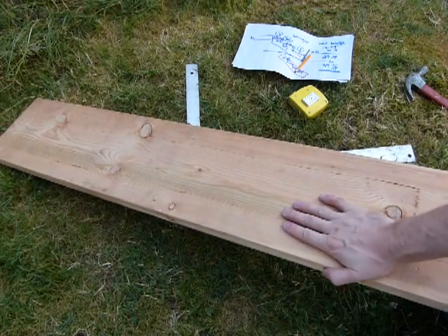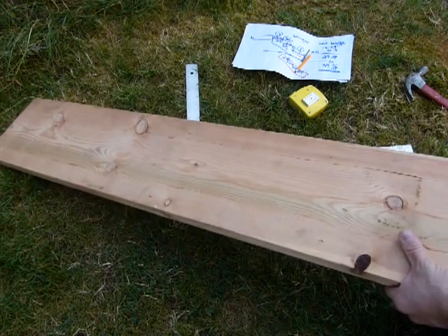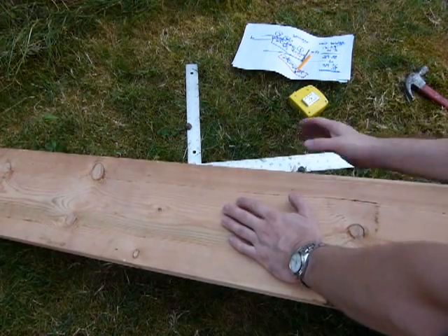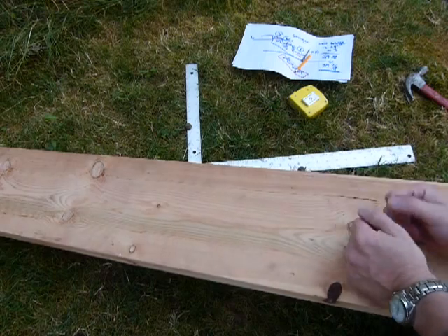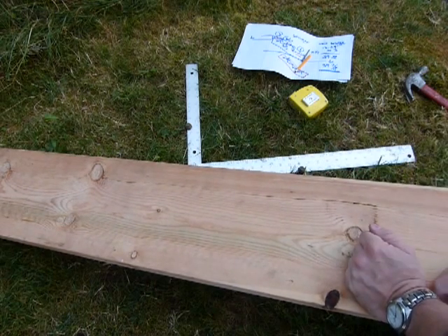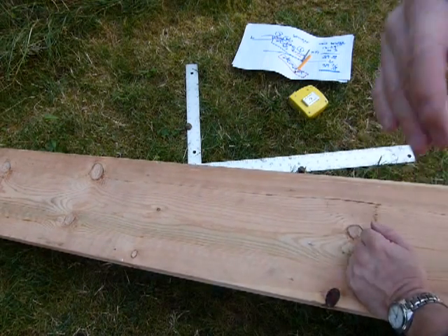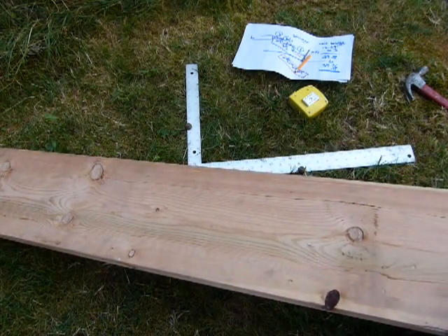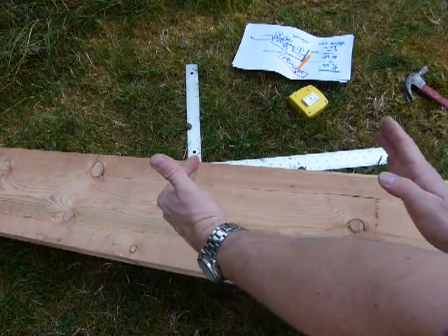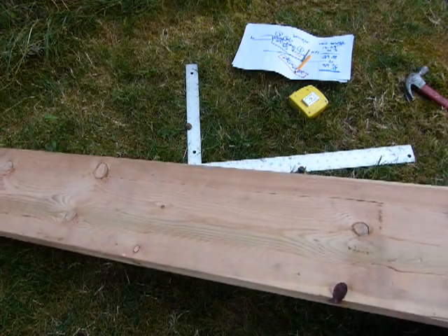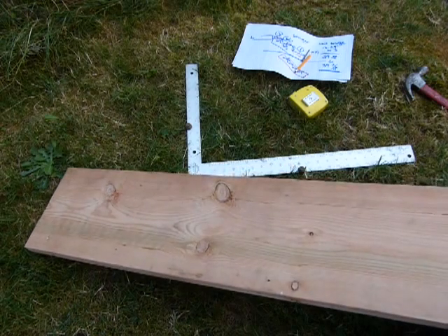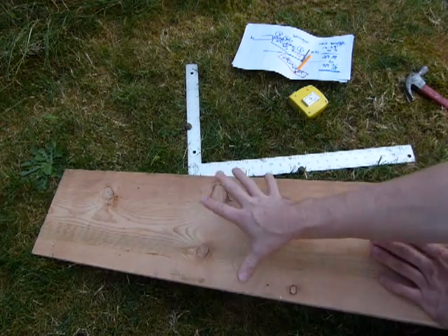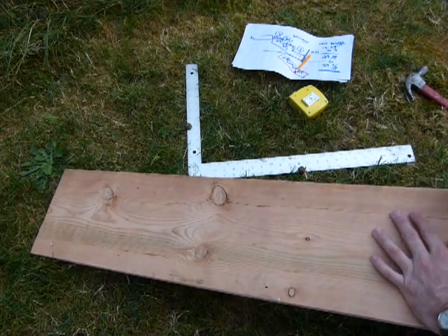And that's why you might want a piece of lumber that is longer than the bare minimum. And remember back, the bare minimum is 4 times your unit bridge if you have 3 runs and 4 risers. So if you have 4 risers, it's 4 times your unit bridge is your bare minimum length to have enough room for your layout. But have some extra room so you can shift your layout depending on how you meet the knots in the lumber. You might need to work around them and shift your layout and redo it again until you're happy with the placement of your knots.